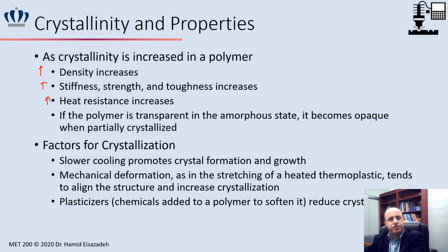There are some factors for crystallization. The first one is that a slower cooling promotes crystal formation and growth, and mechanical deformation is going to tend to align the structure and increase the crystallization.